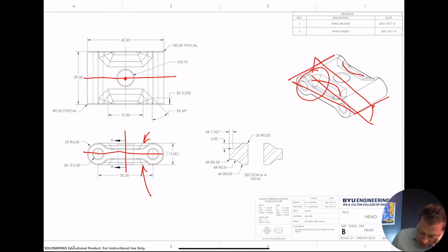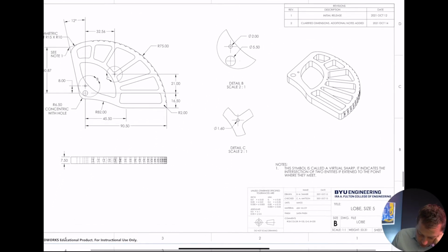I'm going to make this outside shape first, and then it looks like I'm going to create this funny shape that's cut out. I can see that this is the profile of it at section AA, which is shown as just a slice here. So if I get that cross section, I can push it through a sweep profile. So I'm going to do this one with sweep cut. Sweep cut.